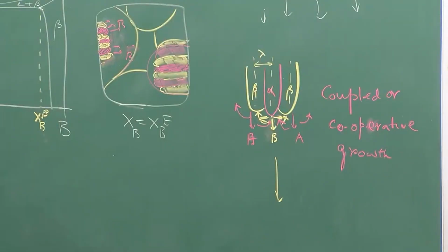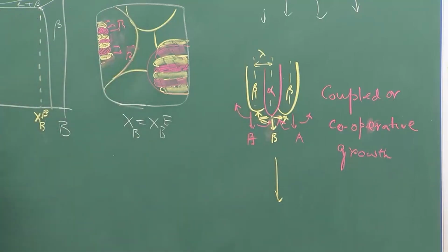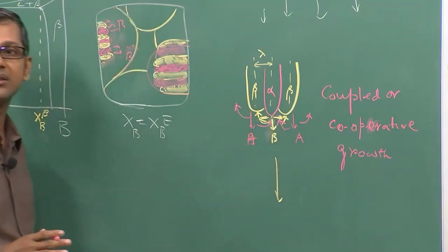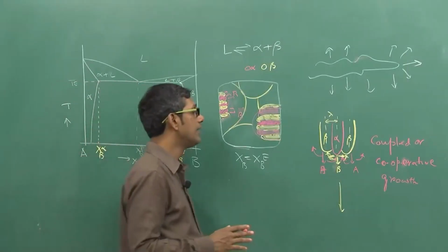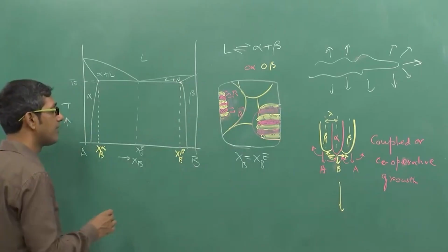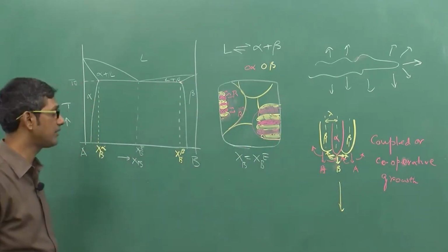So therefore, this growth of eutectic is basically diffusional in nature, and any kind of model or mechanism for the growth of the eutectic must consider how this atomic transport happens across the interface sidewise. So finally, when the eutectic grows, it never has a flat interface, it has a curved interface. I drew that picture, right.